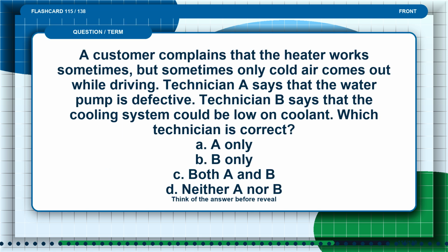Flashcard 115. A customer complains that the heater works sometimes, but sometimes only cold air comes out while driving. Technician A says that the water pump is defective. Technician B says that the cooling system could be low on coolant. Which technician is correct? A. A only. B. B only. C. Both A and B. D. Neither A nor B. Pause and think of the answer before the reveal.